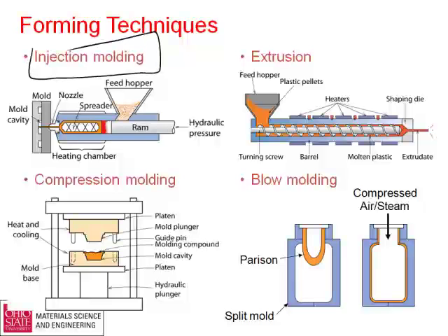Basically what we do is we've got this feed hopper full of little pellets, typically the way the plastic comes in. You put them into basically a big screw here and a ram. You get the material plastic, no voids, no air bubbles in it. Then the ram comes through and fills it into a mold cavity. All of a sudden, there you go. You've got a happy meal toy in every mold cavity. Easy thing to do. If you're making long shapes, you can do extrusion.